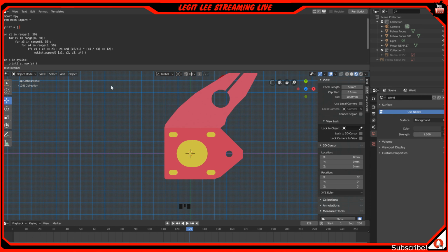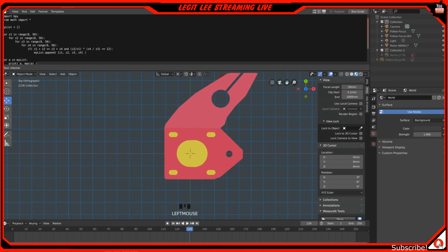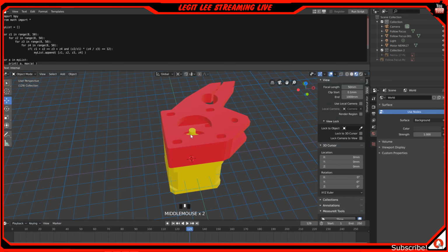Now if we do, we're going to select all this, hit delete, or no, we have to copy. Hold on. So we got this. So I want to make a gear tooth ratio for the first teeth on my shaft. The shaft on my stepper motor is a 5mm diameter shaft, and we want to make 15 teeth on that shaft for a gear, right?